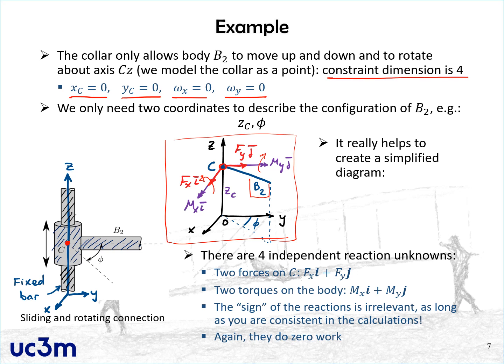This is an example of a simple constraint because it can be integrated. Here I have represented 2 of the equations in terms of angular velocities, but you can clearly write that also in terms of Euler angles. So it can be integrated. The equation is stationary in time. The time does not appear explicitly in the equations, and it is unconditional. There are no greater than or smaller than signs in the equations. They are just equality equations.